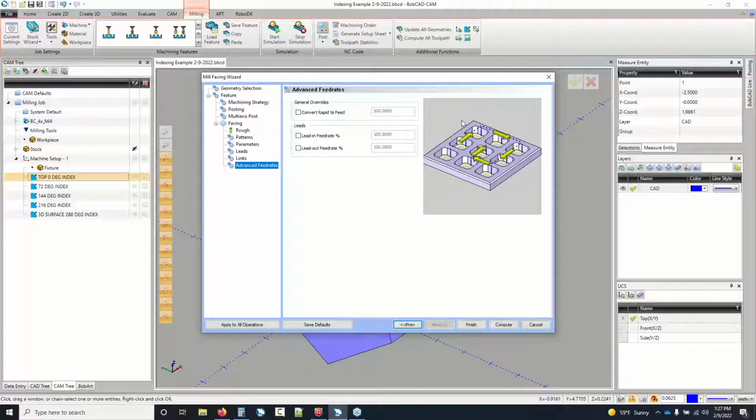The only guys I've talked to that actually had a problem with it were guys that had fixtures sitting above their parts. Bolt heads, there could be a lot of things, but basically you just want to make sure you're safe of any of your fixturing. So be careful when you're running. If you don't have a Haas, it's usually not a problem. And even if you do have a Haas, it's usually not a problem. But just be aware that what that option is going to do is remove any of those G00 rapid moves, and replace them with G01 feed moves.